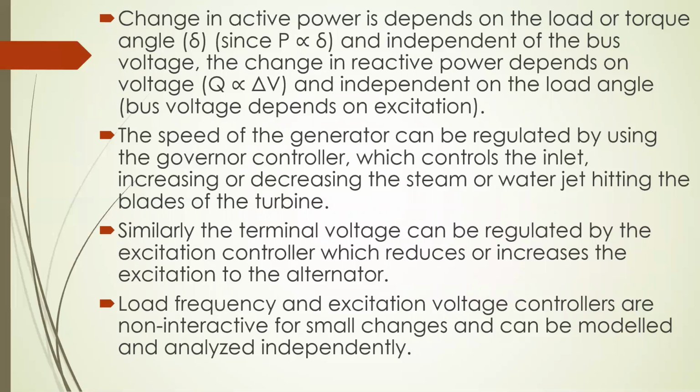If these two values vary, the active power will vary, and active power is independent of the voltage at the bus. Whereas reactive power mainly depends on the change in voltage at the bus, and it does not depend on the load angle or load value.